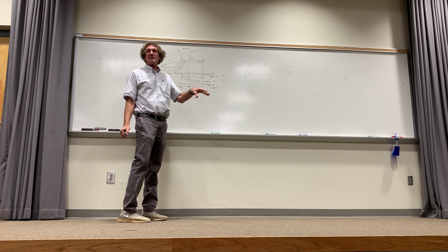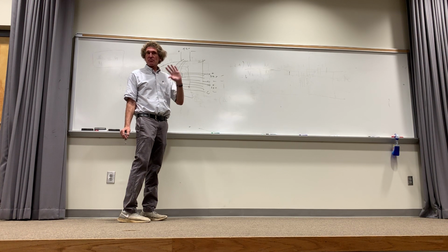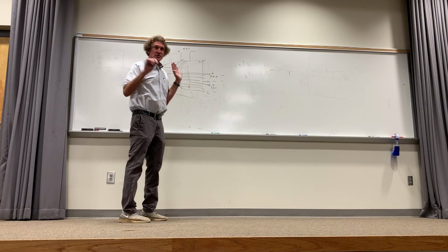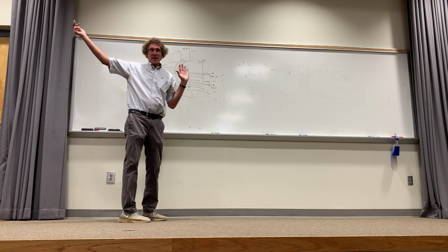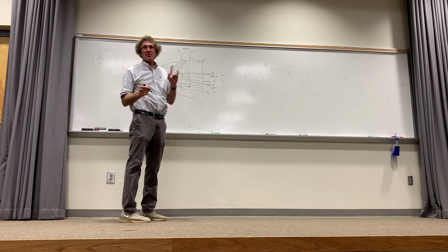And then they'll use that DC signal for their machines, usually. If you guys are working in industry, the IEs especially, you may run into this. You're going to have to at least appreciate how this is done. 7,200 volts is the high voltage line that's running down the street that nobody can get at. Then they have the transformer on the pole that comes off. Those are usually plus or minus 120 to their house.